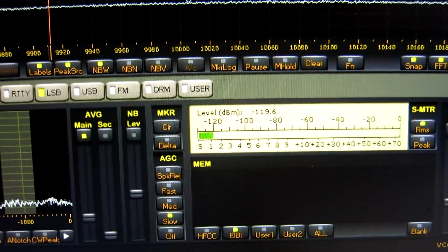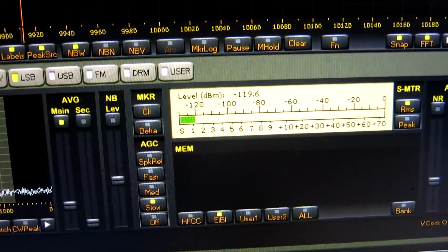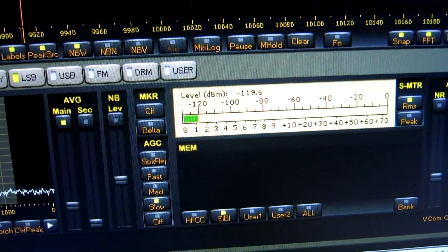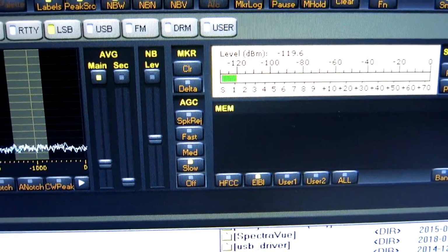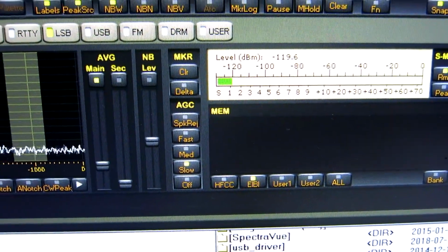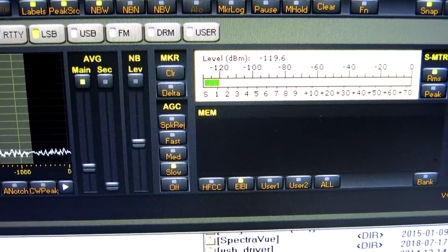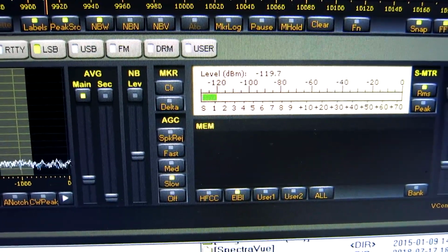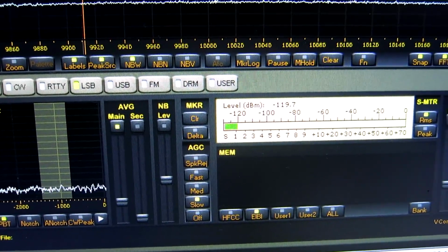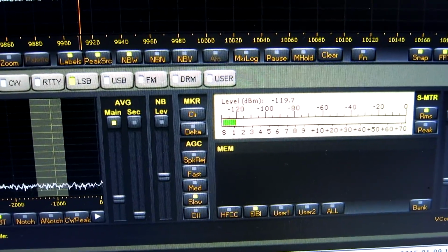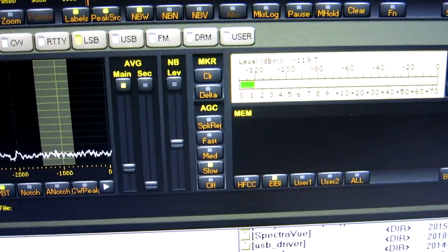This means that the noise floor now, with the noise source off, is at minus 168.3 dBm per hertz, because room temperature is minus 174, and subtracting the noise figure we get 168.3.